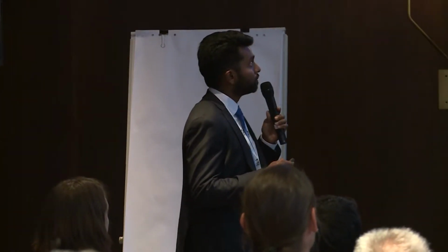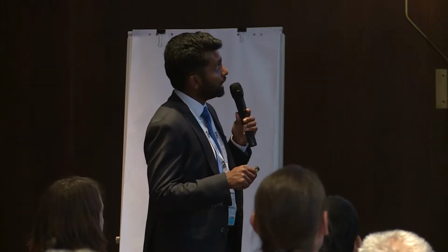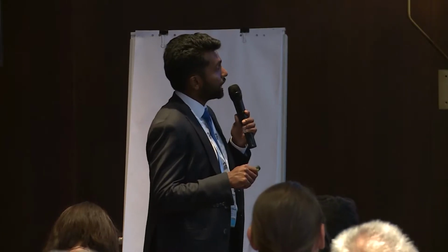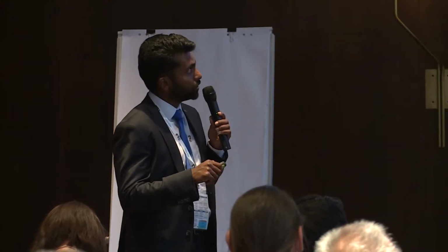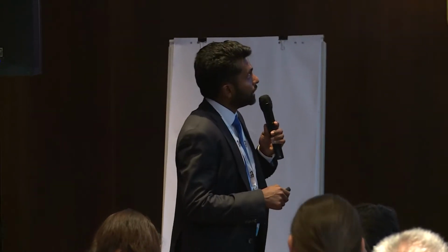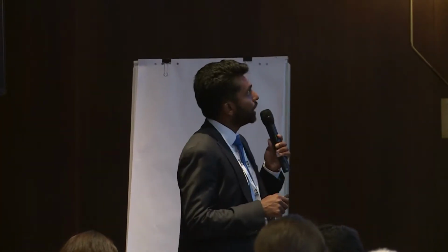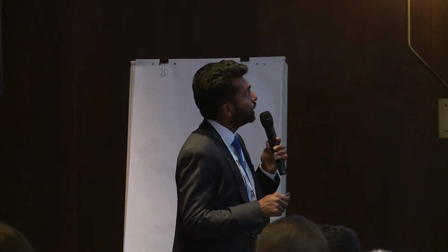We can use the result for all the following steps, because in Abaqus, if we use the option of interpolation, Abaqus can calculate the temperature on each node on the global model for the following steps. So we just need to do this simulation only once. The simulation procedure goes on as I have already explained, only with the new temperature distribution on all the nodes.